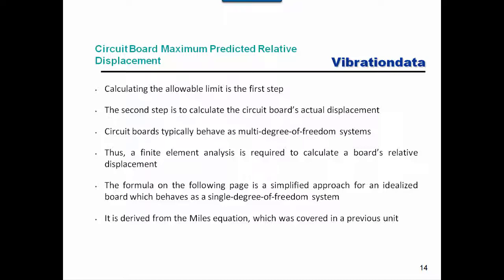Now, circuit boards actually behave in many cases as multi-degree of freedom systems. So we might need to do a finite element analysis to calculate the board's relative displacement under a random vibration environment. But to some extent, many circuit boards tend to be single degree of freedom systems, or even if they are responding as multi-degree of freedom systems, most of the stress tends to be tied up in the fundamental mode.